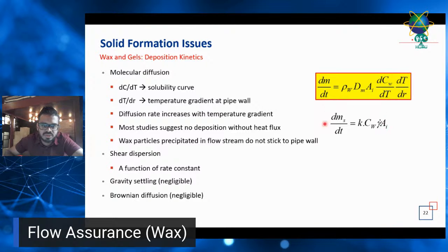There's another term here which is your shear function, the shear effect. But in OLGA we will just use the default value for the shear rate. We don't do any tuning on that. We only do tuning on the diffusion, the deposition rate.